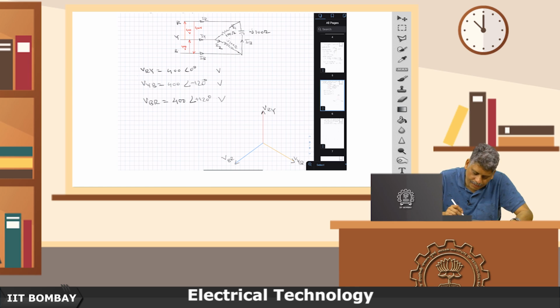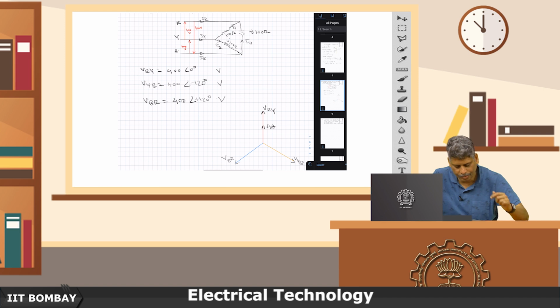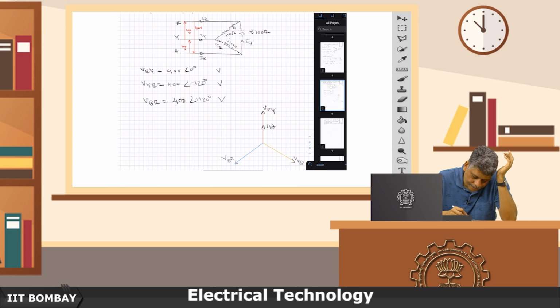Now, let's look at the 3 currents I1, I2 and I3. These are the 3 phase currents. Across RY, a 100 ohm resistance comes. Therefore, 400 divided by 100, which is 4 amperes, should be in phase with the voltage. This is my current I1.